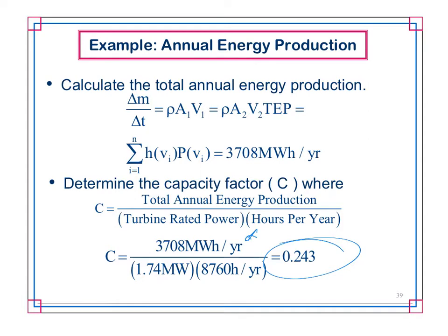So you get 6 meters, 7 meters per second, 90% of the year. And it doesn't go up from 6 meters per second to 12 meters per second and keep bouncing around, because that's very difficult for the turbine to capture. But if it could stay at 7 meters per second for long periods of time, 8 meters per second for long periods of time, that's a better site than one that has a higher average wind speed, but it's constantly bouncing up and down, because the turbine just can't respond that quickly to those changes. So that's kind of where we come up with capacity factors.